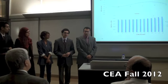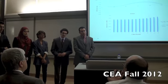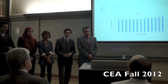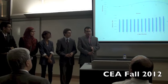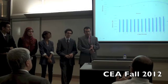Regarding the 3D model, what do you mean by 3D model? You mean area elements, shell elements, solid elements, if you need, cable elements, everything. Well, we use cable elements and frame elements for the pylon, and that's fine. For the deck, we use the grillage instead of area elements.